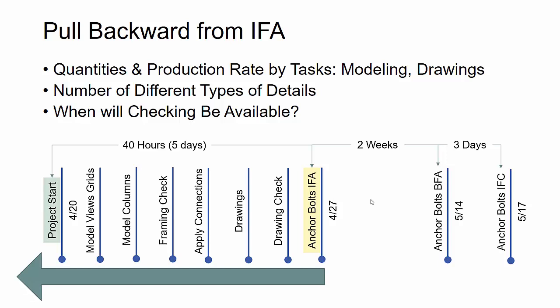Now, what I typically see on a submittal is that when you go out for approval, the back from approvals are usually contractually required to come back within 2 weeks or 10 business days. And sometimes that gets compressed to 5 days, depending on the job. So when you look at that and you actually start mapping out when you are going to ramp up resources versus ramp them down, you see that, okay, this detailing package is done. When's the next submittal that's required? The next IFA, the structural. When do I expect the back from approval to come back? Is that going to take away resources that are working on the next submittals or the next phases? And when do they overlap on top of each other? So that's something important to understand.